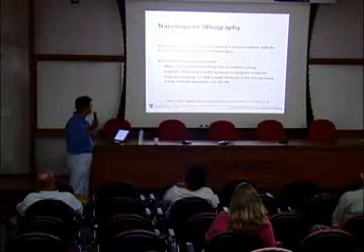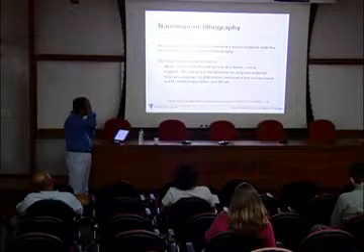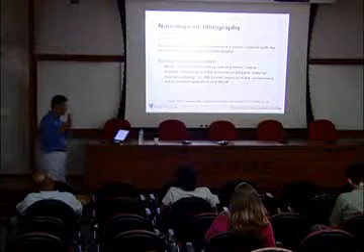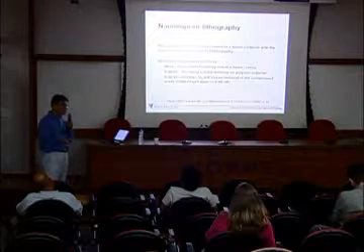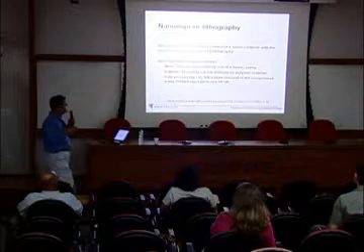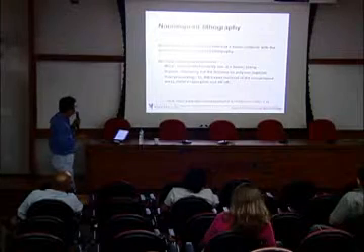It's similar to micro contact printing, but this one is a more precise handling in terms of pressure and temperature and also the mold. The mold is usually fabricated by electron beam lithography. So the small pattern can be as small as 2 or 3 nanometers in terms of size.